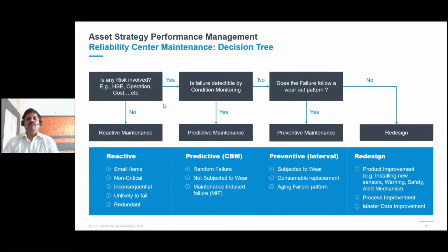So one of the well-known practices we all know is reliability centered maintenance, which has been used in the industry for the last 20-30 years, and which could be a solution for the challenges we discussed on the previous slides. Basically, the reliability centered maintenance method helps us to understand our equipment in more detail, and then based on your maintenance strategy or your asset requirements and its position in your operational line, it helps guide the adoption of a right maintenance strategy.